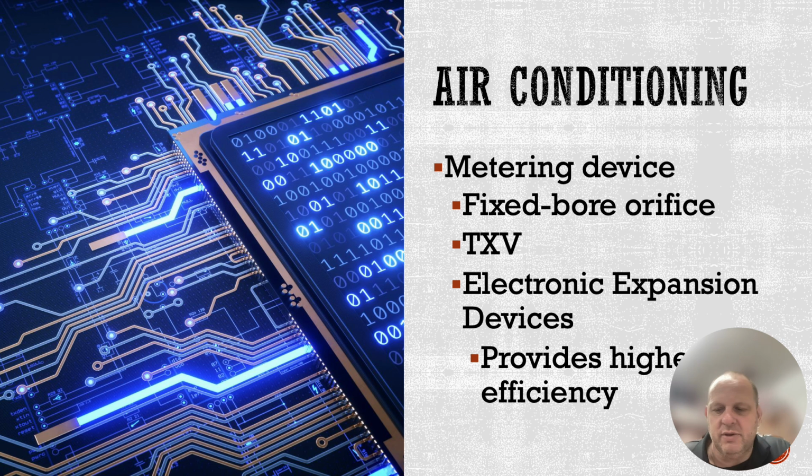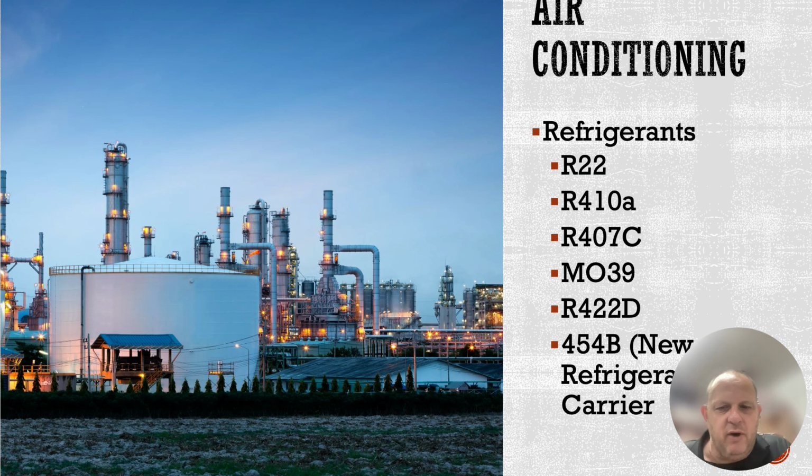As far as our refrigerants are concerned, 410A is going away because they've deemed it to be a problem with global warming. 400 series refrigerants in general, the older ones, are going to be moving away, and we're going to be moving into new refrigerants that are mildly flammable or have a mixture of refrigerants in them that are flammable themselves. R22 has basically been decommissioned from a lot of different units out there. 410A is about ready to be decommissioned next year, 2025.